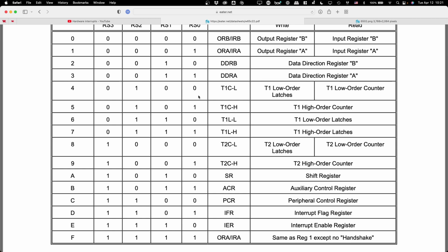Now one thing that's really annoying: they don't make the 6521s anymore. They do still make the 6522s. This is a big problem in restoring old Commodores because if the keyboard's not working correctly, 99 times out of 100, it's because of a bad CIA, complex interface adapter, which is the 6521 chip. And they don't make them. So where do you get the working ones? From other Commodores. You have to Frankenstein these things.